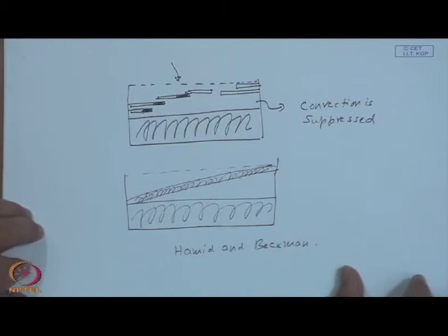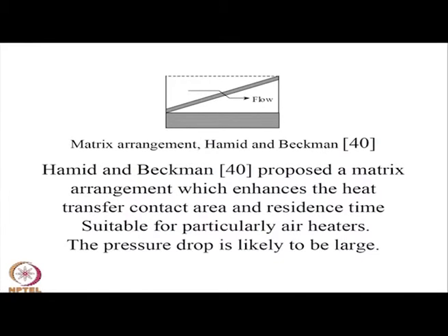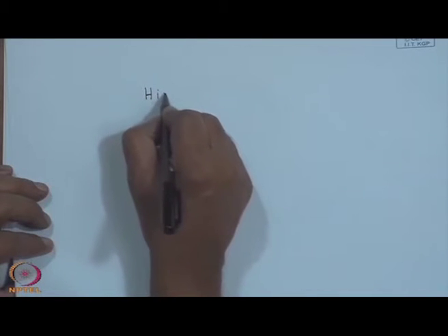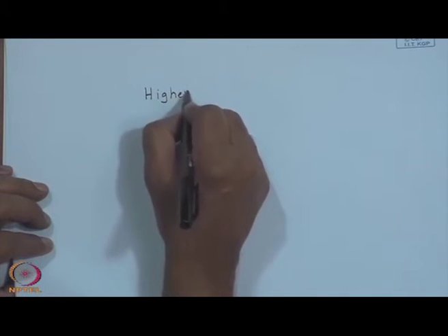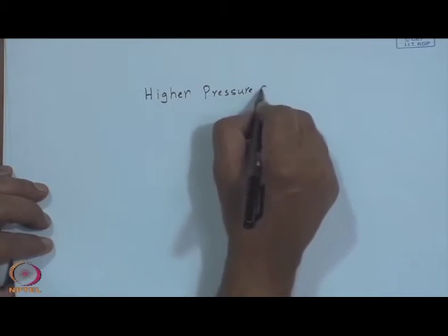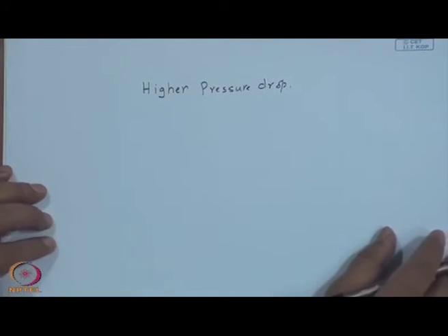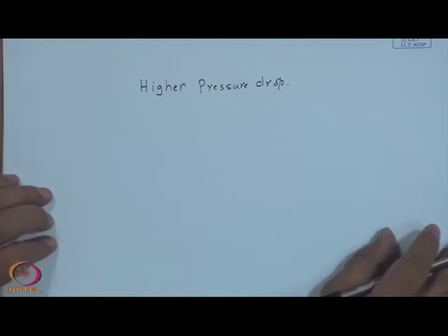But all these configurations in general have higher pressure drop. In fact, it is almost a thumb rule that you cannot enhance heat transfer coefficient without enhancing the pressure drop. The other way around is perhaps possible.